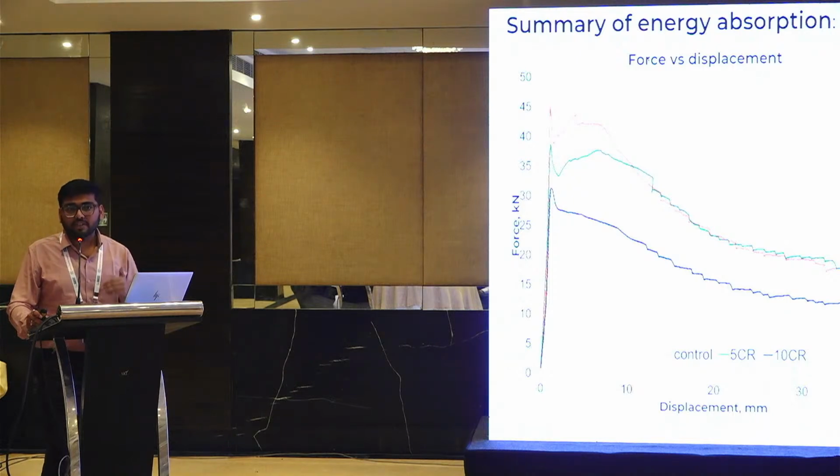If you want to achieve a similar 10% improvement with the steel fibers, you need to dose an additional 15 kgs of steel fiber in the mix. But the same thing can be achieved by dosing 5% of the crumb rubber. So this is one notable change, that we can use this material in improving the seismic behavior of the concrete. Damping studies we are presently undertaking, so I do not have those results here.